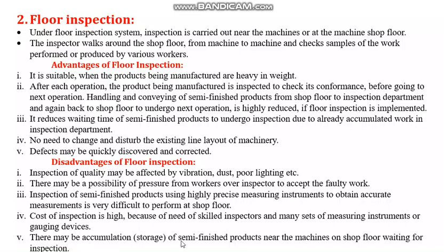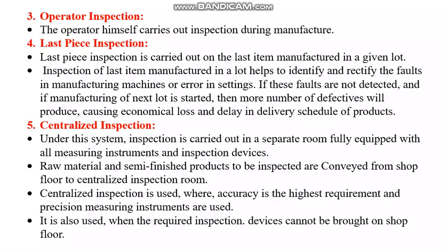Then there may be accumulation of semi-finished products near the machines on the shop floor waiting for inspection. Suppose unless the inspector comes and checks, the parts will not move further. So here also time may be wasted. As an advantage we said no time will be wasted because the inspector is coming, provided he comes immediately. But if he fails to come immediately, then it becomes a disadvantage.